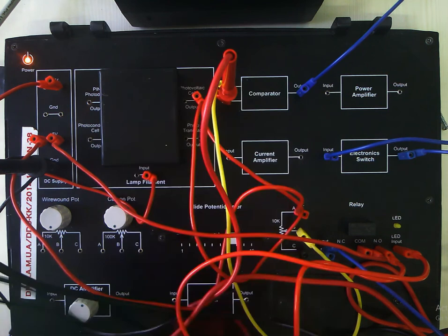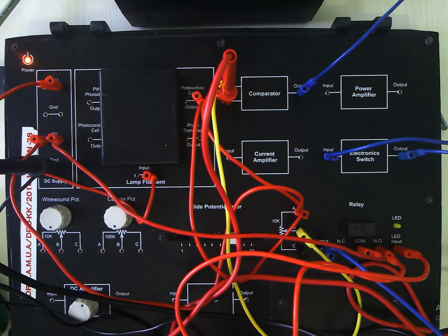So that's it. Now in the third part of this experiment, we will try to develop a circuit that will operate in such a manner that whenever there is darkness, then it will operate the LED to on, and when there is light the LED will be off. So this application is also called a Twilight switch, and you can definitely develop this basic project as an assignment for yourself.